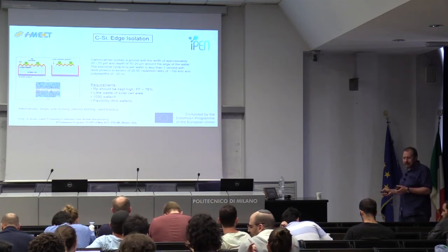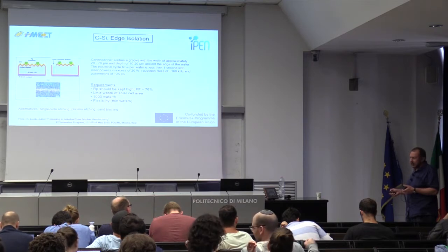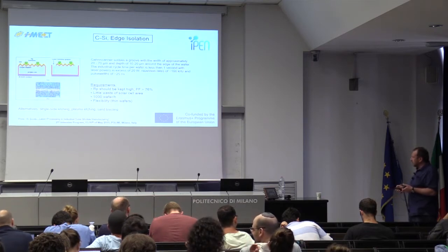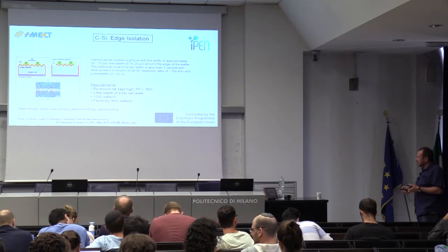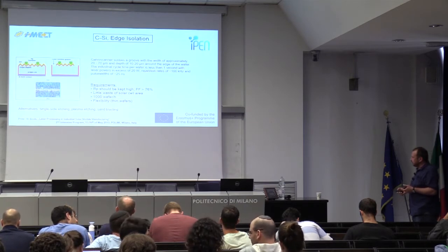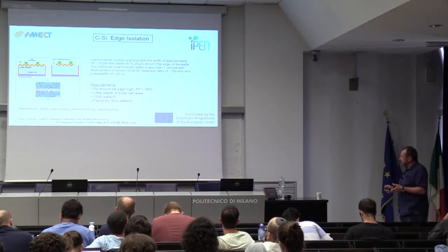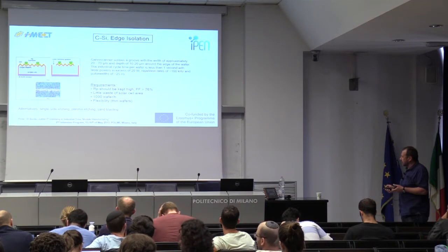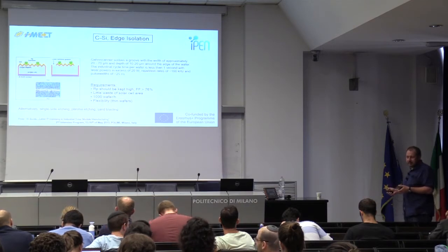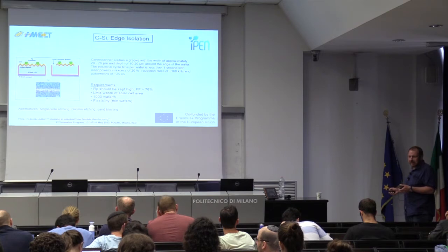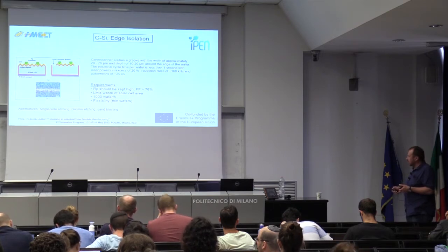The ultraviolet laser just gives you a smaller groove, and the loss of area is limited in this way, and you have a nice scratch at the edge. And this process is very fast. What I've read is about 1 second per wafer.